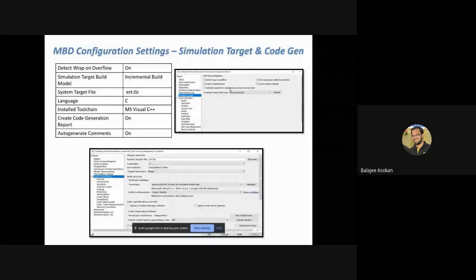Now the OEMs are coming up with different automation solutions for when my model is missing out on these parameters. They have created their own templates. So when I start a development, I need not open a Matlab model from scratch and try to change these parameters one by one. They will have a set template model, and I can just open the template model and start simulating.